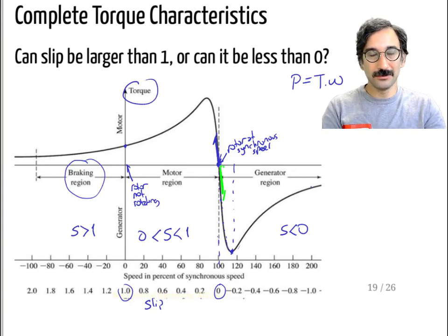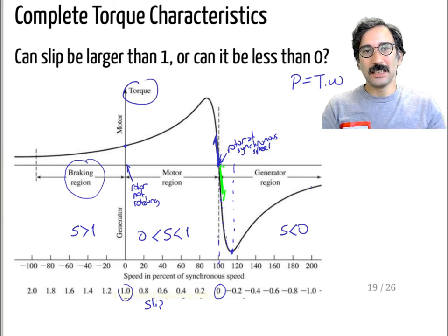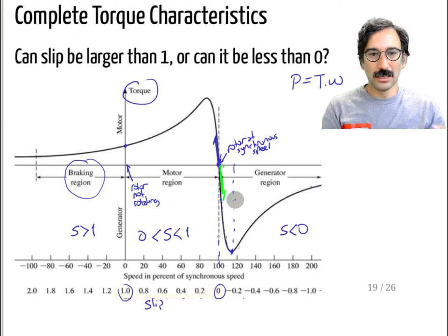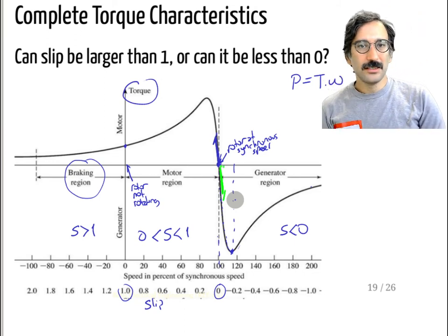foot on the brake pedal, then at first they don't apply the mechanical brakes immediately. Okay, so what they do is the variable frequency controllers adjust the operating modes, then your electric motors become generators. So now it is applying some negative torque, so it is slowing down your car, but while doing that you are charging your batteries in the generating mode. Okay, so that is the same analogy with the synchronous machines.